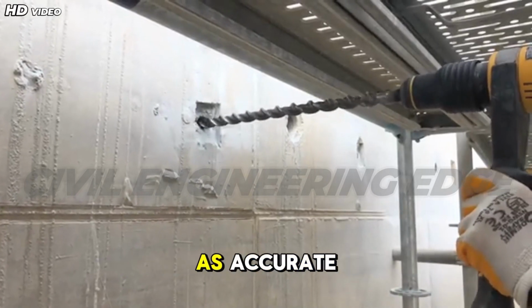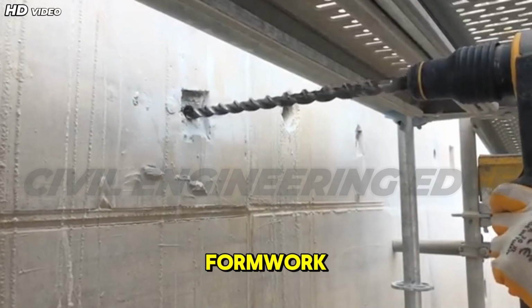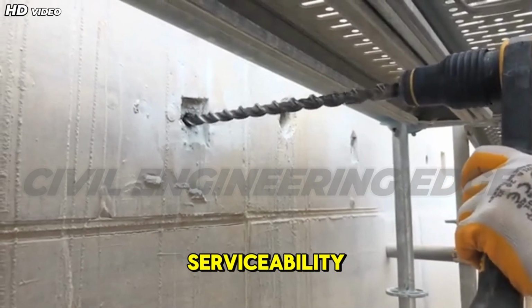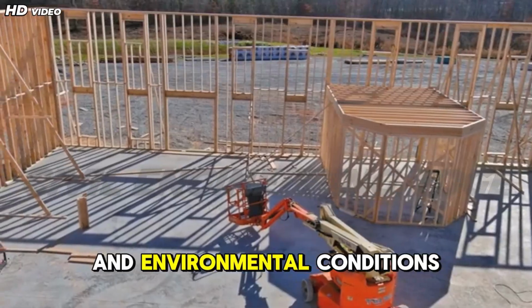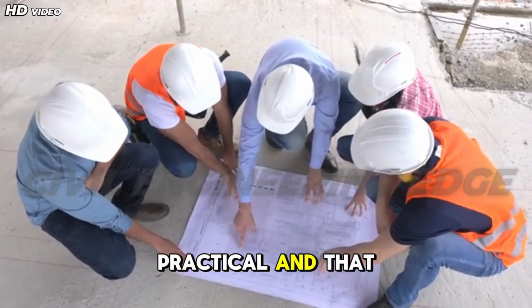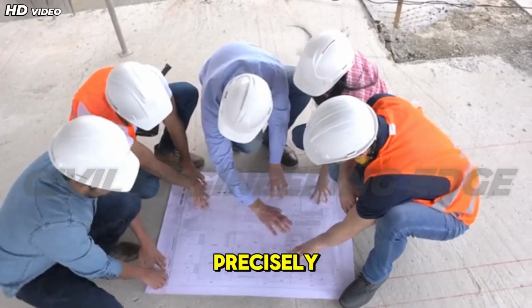Construction practices such as accurate placement of reinforcement, proper alignment of formwork, and adequate compaction of concrete directly influence column strength and serviceability. Site constraints, labor skills, and environmental conditions must be considered during execution. Engineers should ensure that drawings are practical and that site teams understand the importance of following them precisely.